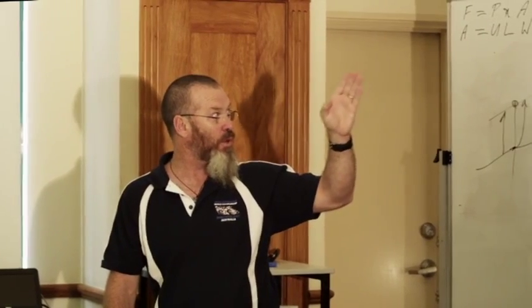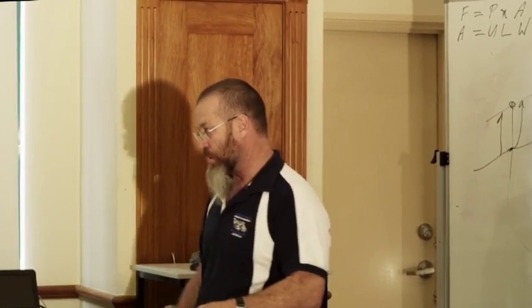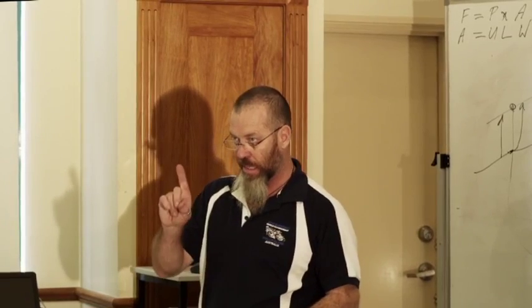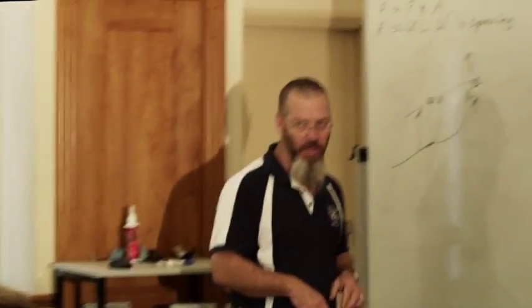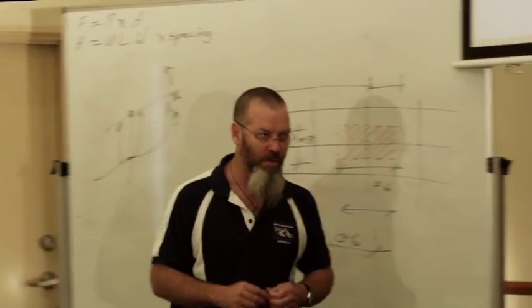The same with your creepers, plates or creeper hip plates. You're not going to do them in task 57, by the way, but that's what you do. That's the one you use. You use your table 9.21, sorry, connections from 9.21 for those. Okay? And we spoke about rafters to ridge already. So when you get stuck, in task 57, you may or may not want to write this down. In task 57, the connection for your rafter underpurlin comes from table 9.21.